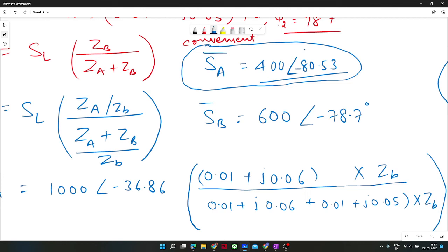The base value in the problem is a single one. If any problem is given with per unit, then you have to consider the same base value for the entire data in voltage, in kVA, everywhere. Okay. There is nothing mentioned explicitly that the base value for this transformer is this and the base value for another transformer would be that. As long as this condition is fulfilled, you can go ahead with the same base value. Fine. Yes. Okay, perfect.